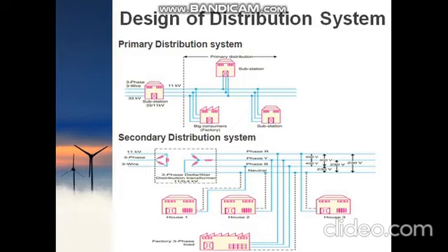And after the 11 kV, the primary distribution will start, which is going to feed internal substations in the mega cities or big consumers like big factories and GIDC industrial areas and all. After this primary distribution substation, the secondary distribution system will start. You can see that up to the primary distribution substation, there will be a 3-wire 3-phase system, and in the secondary distribution system,